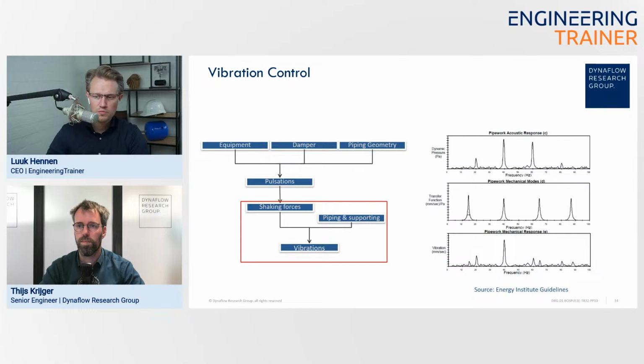If you would push it higher to, for example, 600 RPM, which is 24 hertz, it is very difficult for piping design to remove those mechanical eigenmodes at those frequencies. I think this is in line with something you just mentioned. Those higher frequencies are a challenge, so you have to look into details. Is there overlap? Will there be mechanical resonance?